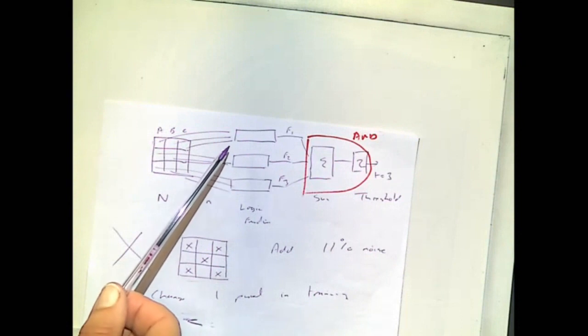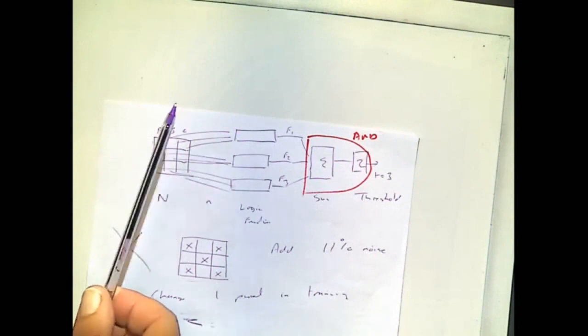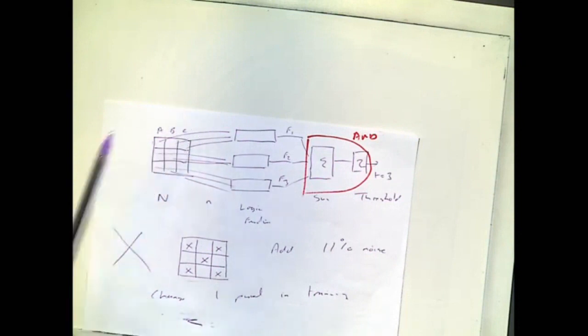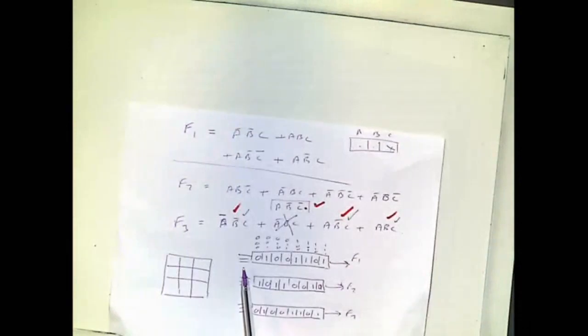So the total number of functions will be the resolution divided by the sample size. The second thing is the cost of building the functions in terms of memory. Go back to this diagram. 3 inputs, implementing it in a memory, I need 8 bits of memory. In general, n inputs, I need 2 to the n bits of memory.